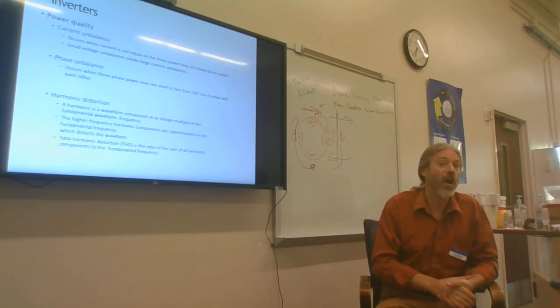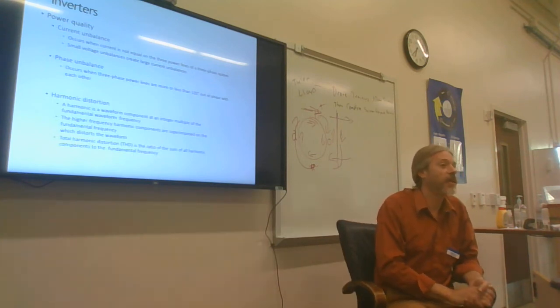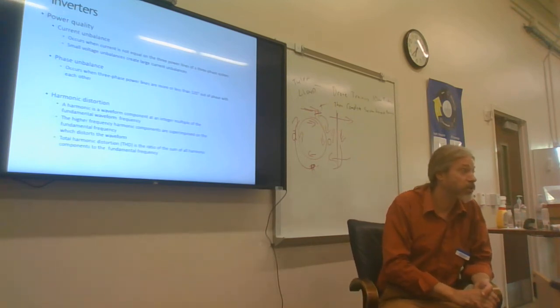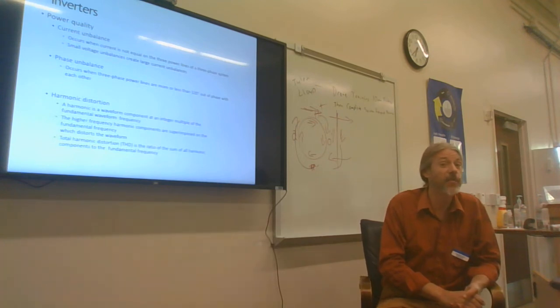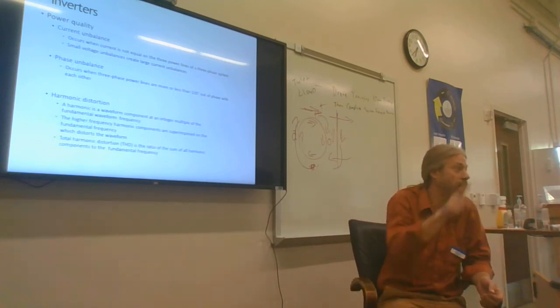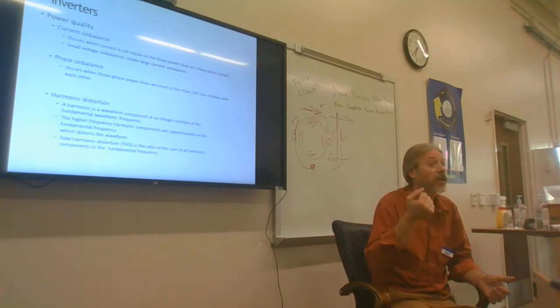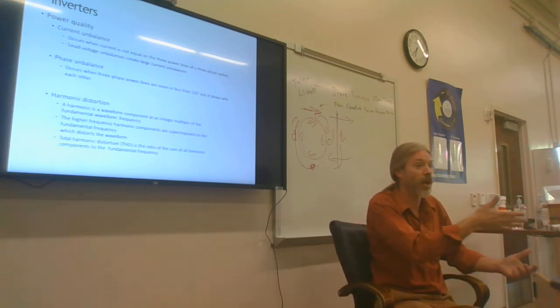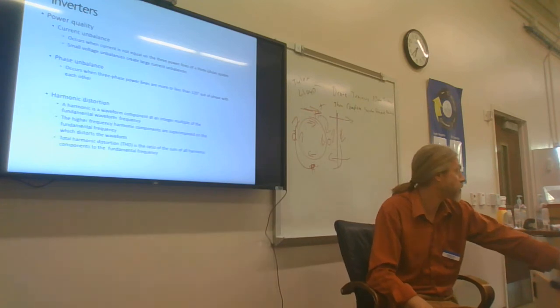All right. Oftentimes, what's happening is one of the phases has a lower voltage, so the other 2 are trying to make up for that loss in that cycle, so they end up having a higher current demand. They're asking for more power to make up for the loss of power in one of the 3 phases.